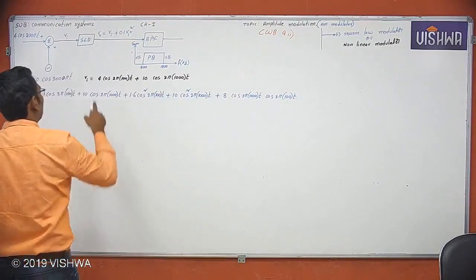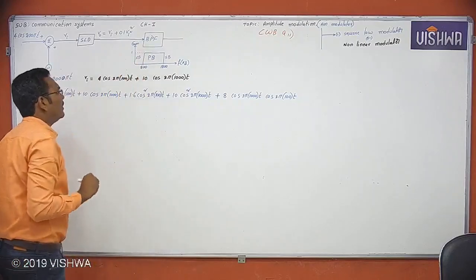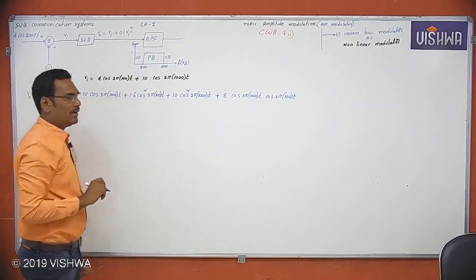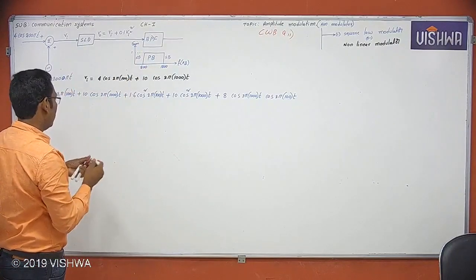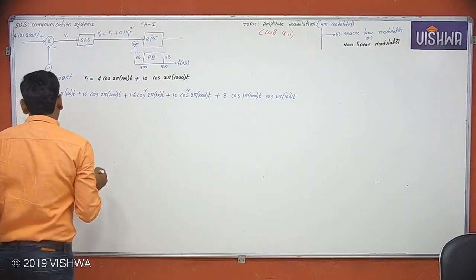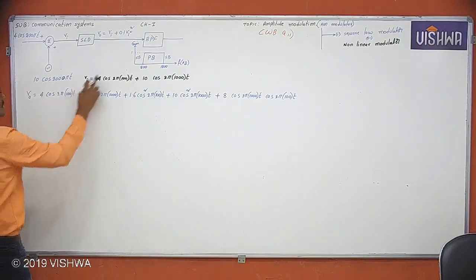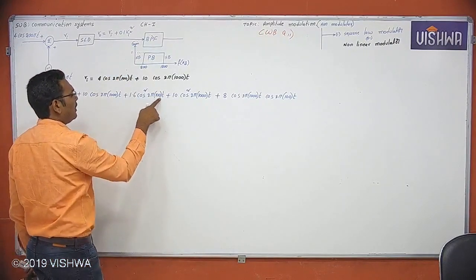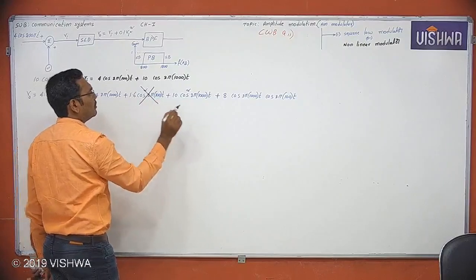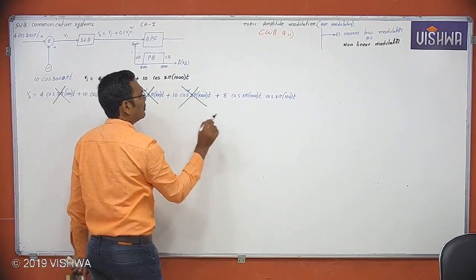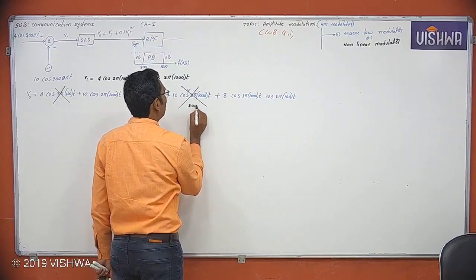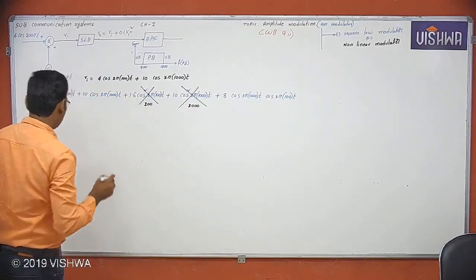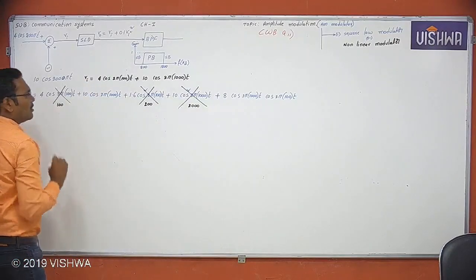Now the square law device output is passing through a band pass filter whose pass band is from 800 Hz to 1200 Hz. Now see here. What is the frequency? 100 Hz is within the stop band, not allowed. 200, not allowed. 2000, not allowed. This is 2000, this is 200, and this is 100, none of which is allowed by our band pass filter.